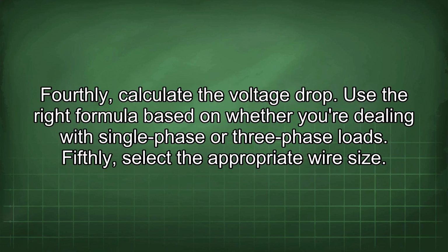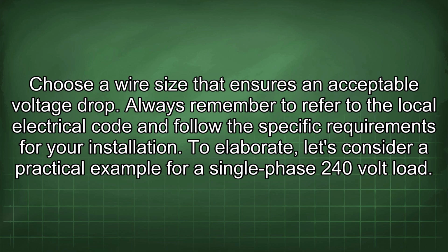Fourthly, calculate the voltage drop. Use the right formula based on whether you're dealing with single-phase or three-phase loads. Fifthly, select the appropriate wire size. Choose a wire size that ensures an acceptable voltage drop. Always remember to refer to the local electrical code and follow the specific requirements for your installation.